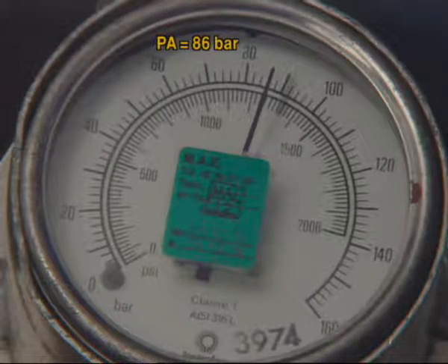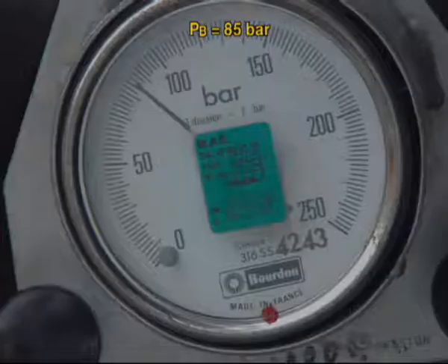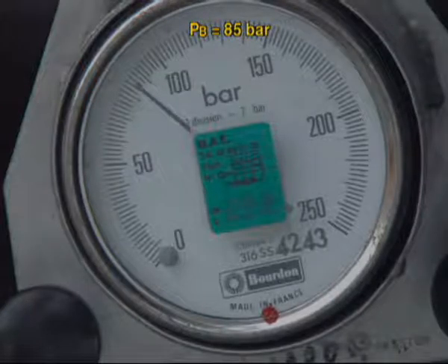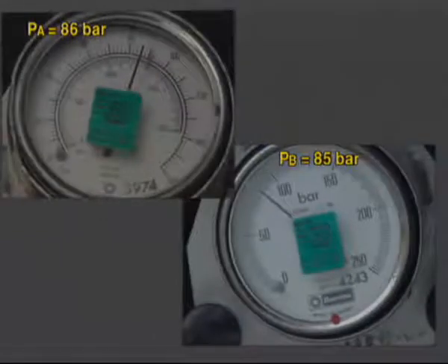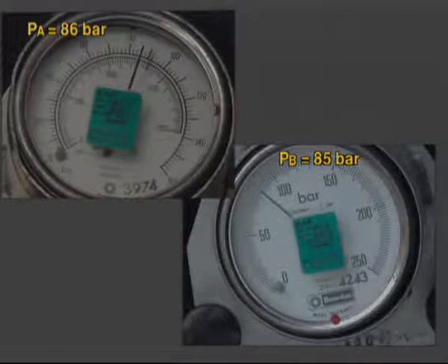After 5 minutes, check the pressures. Open the top charging valve, read and write down the pressure, and then close it. Open the bottom charging valve, read and write down the pressure, and close it. Make sure that the pressure at the top and bottom charging valves are the same, plus or minus 1.5 bar. If not, you have to do the procedure again, starting from the step where the floating piston must be moved to the top of the bottom chamber.